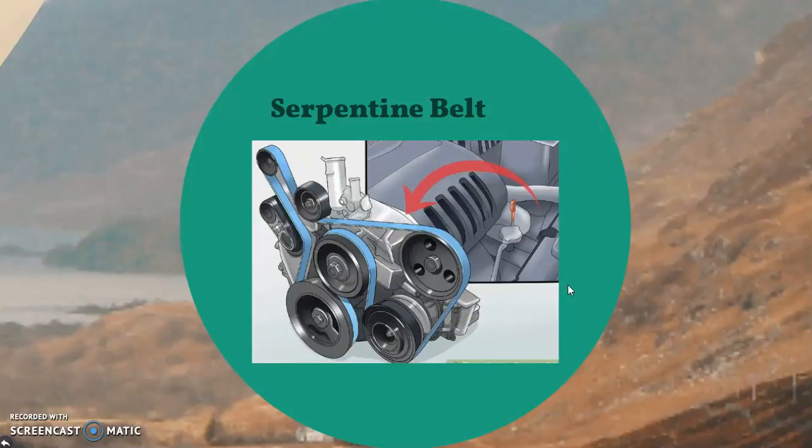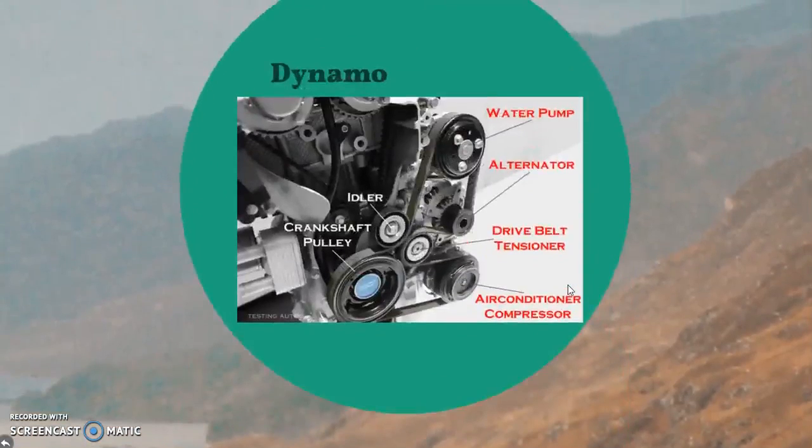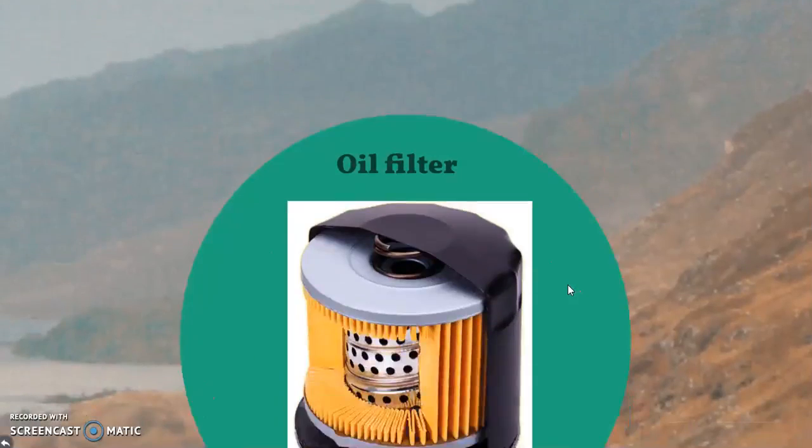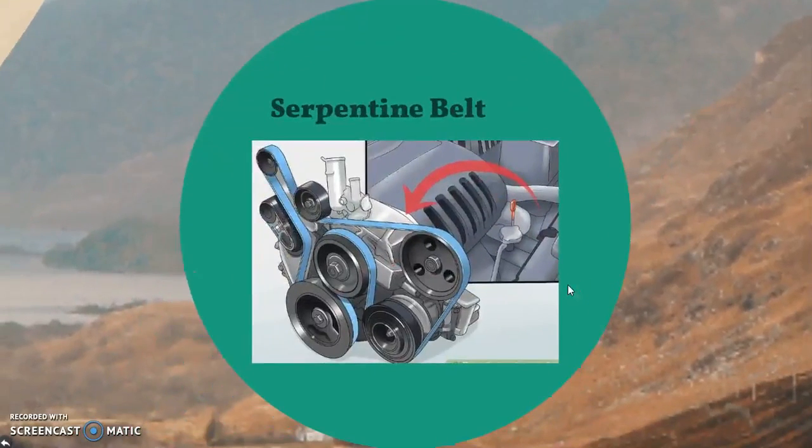What it does is basically link or connect all of these wheels, such that the tangential velocity at the serpentine belt and at the edge of the circular moving part is the same. And hence, in a way, it links or couples different moving devices. This is important when we consider the transmission system.